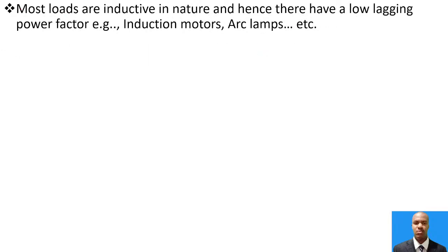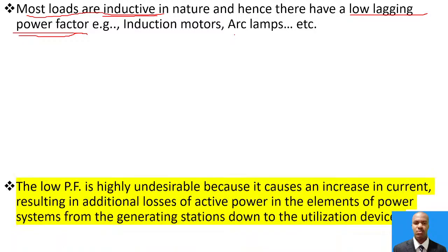The reason why power factor is important is that in most cases our loads are inductive in nature. Being inductive, they consume a lagging current at a very low lagging power factor. Such loads include induction motors, arc lamps, and sometimes fluorescent lamps.